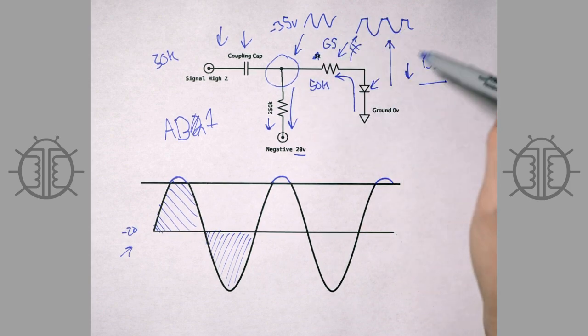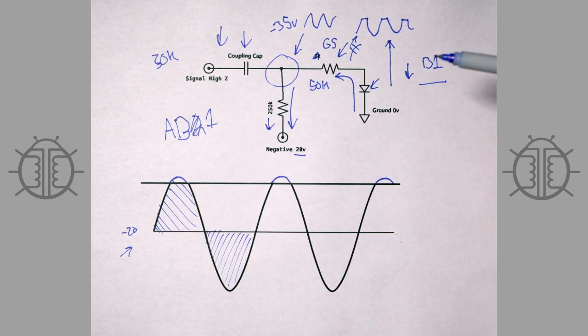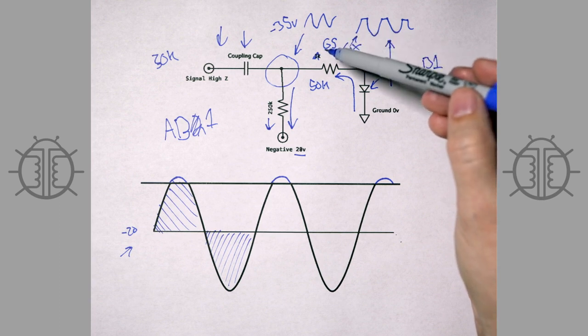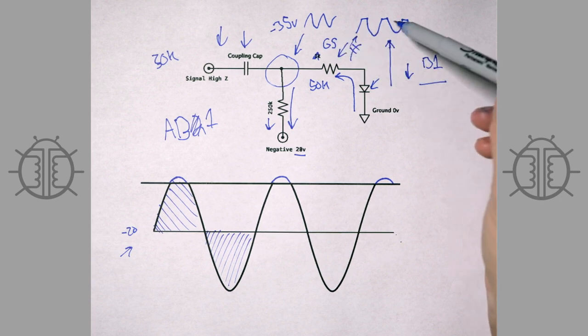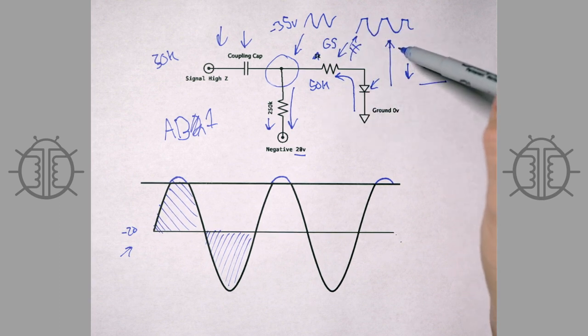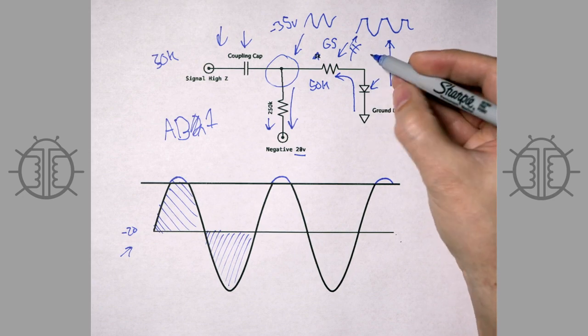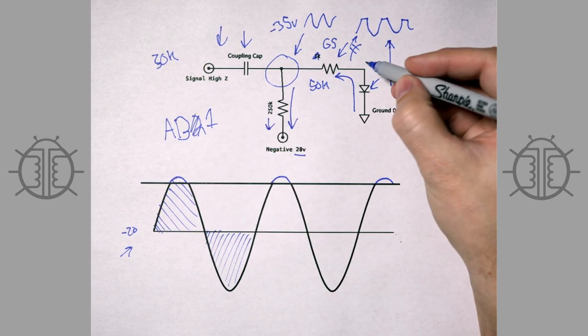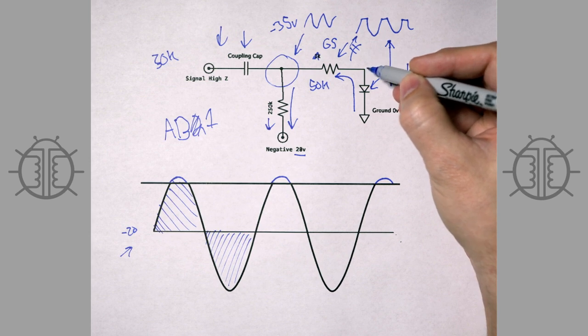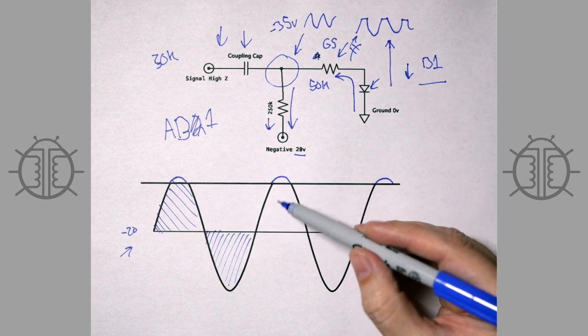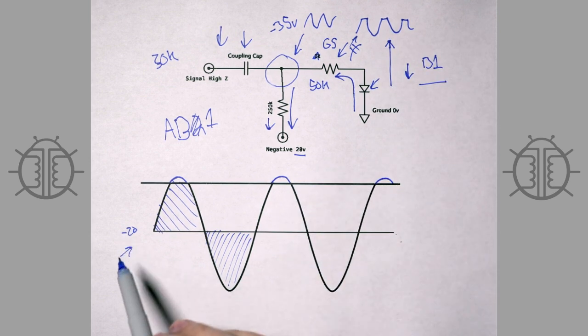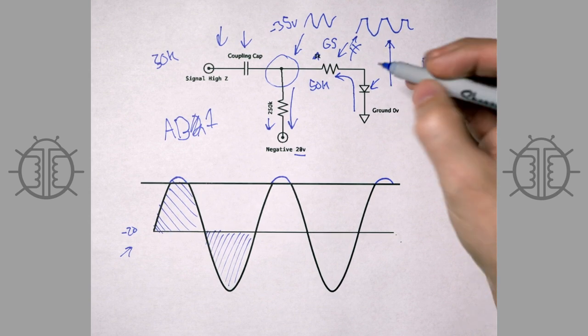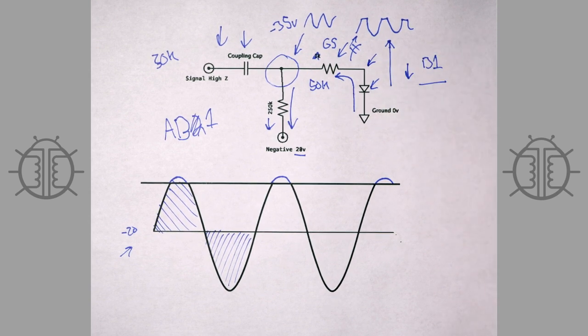But the problem with all of these, except for the follower stage one, is that they just cause the amplifier to recover from blocking more quickly. Over here, as long as we're still in AB1, we're still having a temporary situation where we're half-wave rectifying to a more negative voltage than we want right here. So what is the solution for this? I will show you.